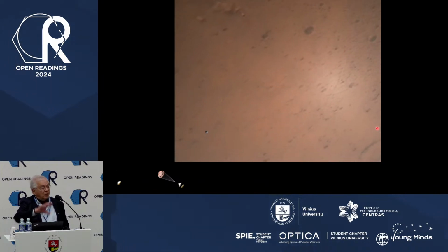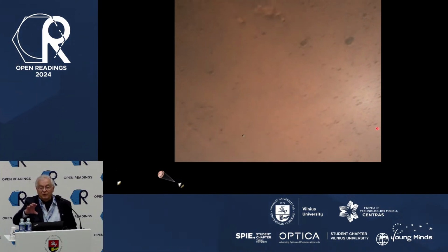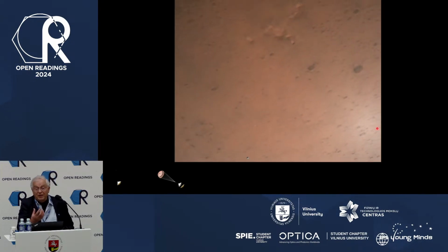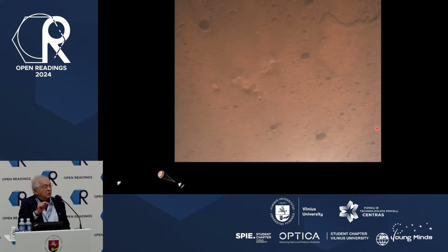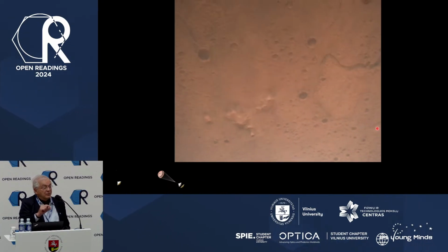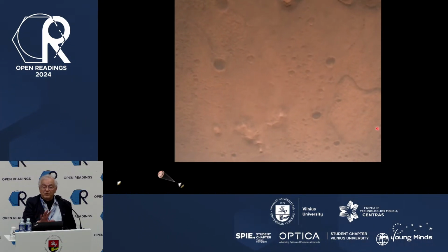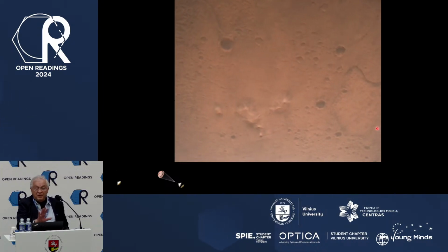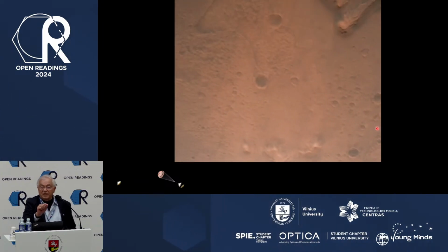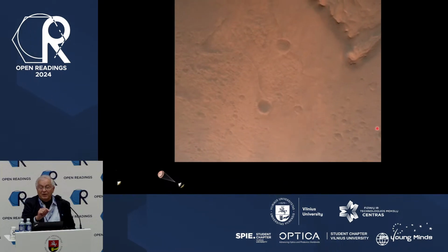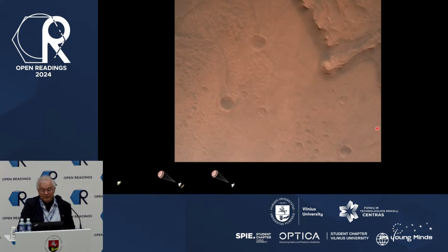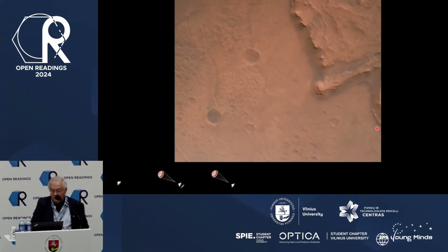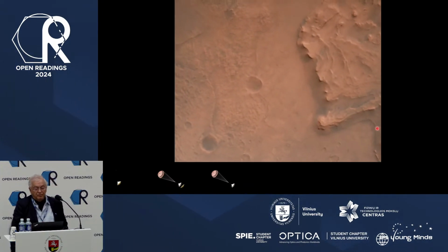Now, some of you will be wondering, why is it wobbling? For two reasons. One, you are on a parachute, so that kind of swings as you are coming down. And number two, we wanted to land in a very specific area, so we take pictures of the surface and we keep moving the spacecraft to make sure we are centered at the area that we want to land at. That's all being controlled autonomously on board the spacecraft. Altitude 7.4 kilometers. Now has radar lock on the ground. Current velocity is about 100 meters per second, 6.6 kilometers above the surface of Mars.